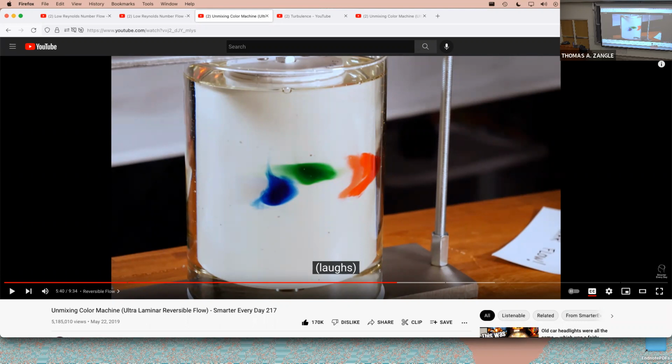So turbulence creates more activity, that's correct, because it's mixing more effectively. In this case, we are increasing entropy because of molecular diffusion here. It's just that the flow itself is time reversible. We have kinematic reversibility, but there is no effect of inertia in this flow. We're not increasing the entropy because of the flow itself.